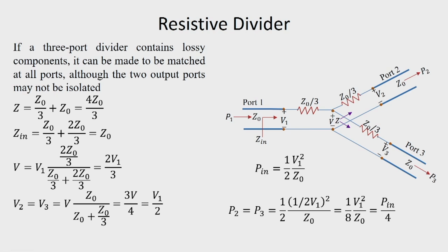The power gets dissipated in these resistances. So, as it is a reciprocal network, we can write the S parameters. We have already said that S11 will be 0, and also S22 will be 0, S33 will be 0, and if you consider S21 for example, power to port 2 from 1, that will be mod S21 square and this will be 1 by 4.